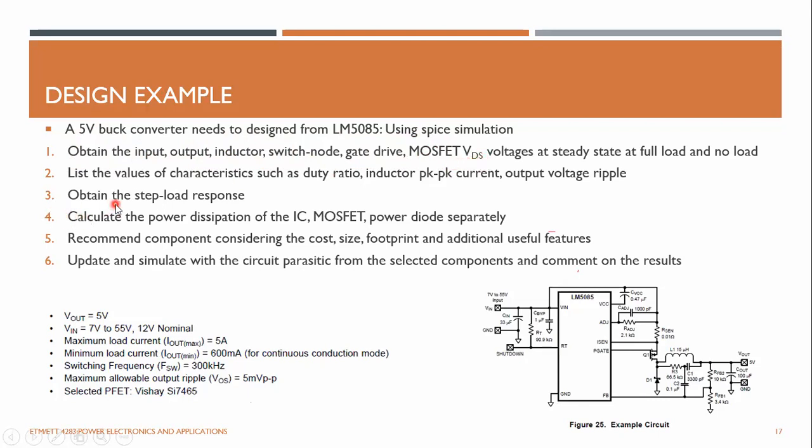You also need to obtain the step load response, and calculate the power dissipation of the IC, MOSFET, power diode, and everything. And finally, recommend components considering the cost, size and footprint, and additional useful features.